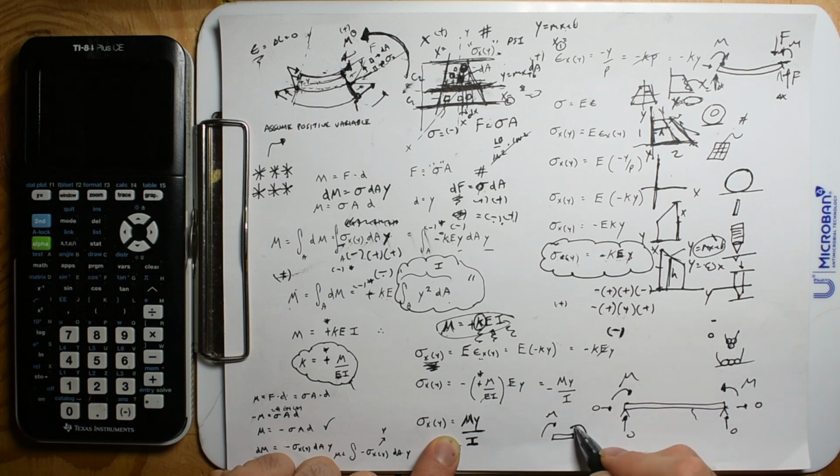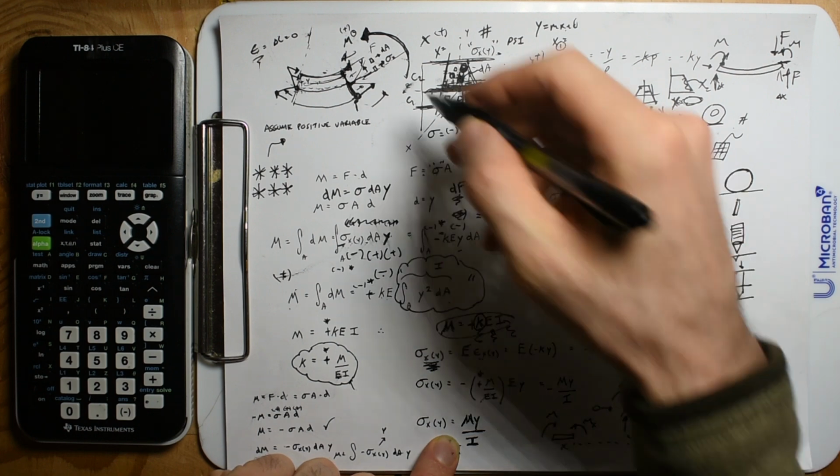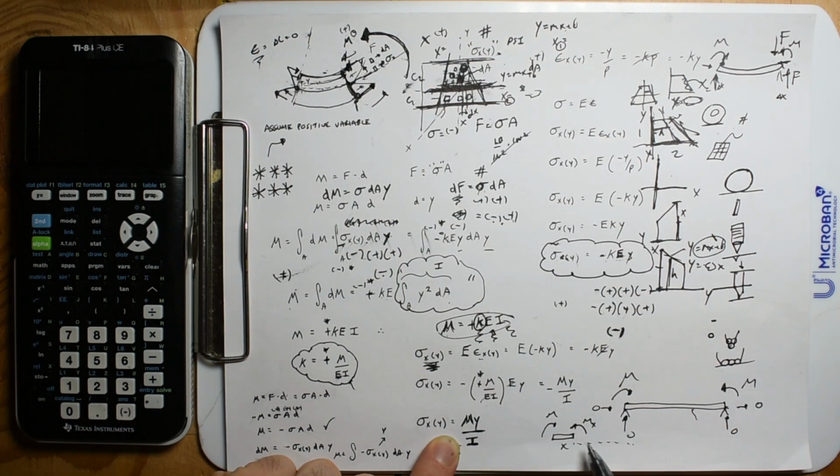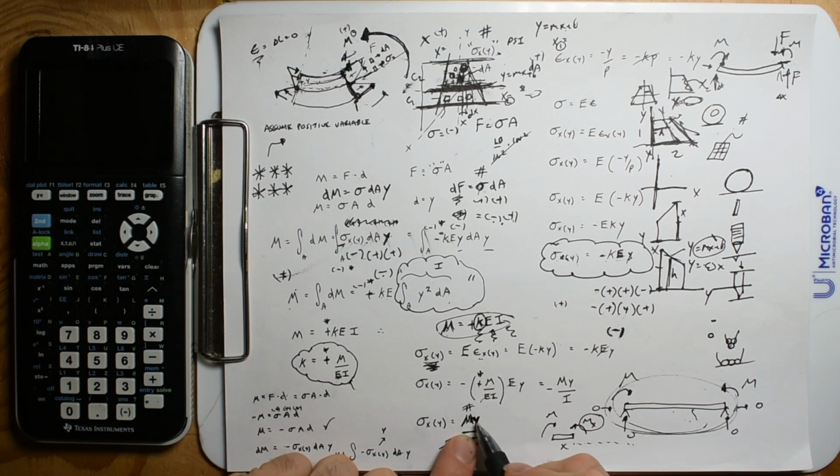It has to be matched by the equal moment too, because this thing's not spinning. And so we have the moment for every point along here, x. And then that moment at that face is these forces. And so we can know this moment due to free body diagrams of the beam. We can input that number right into there. We know the y distance.